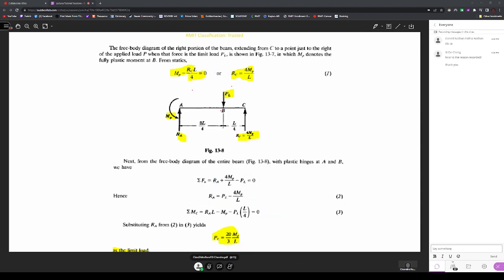When the load keeps on increasing to the maximum load, or the plastic load, the points on the structure that first become fully plastic we call plastic hinges. These plastic hinges we indicate with circles, and with the help of those plastic hinges, we can calculate the plastic loads.